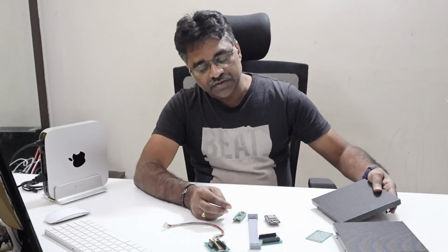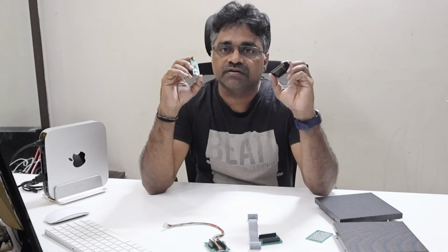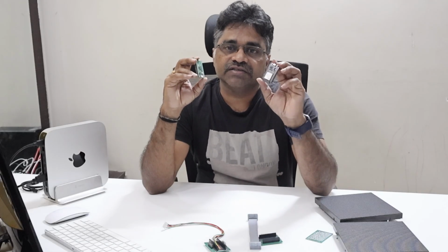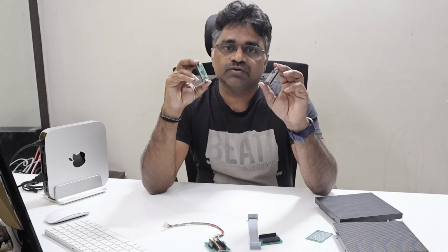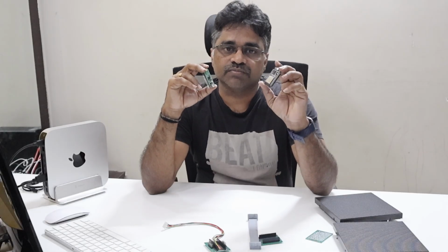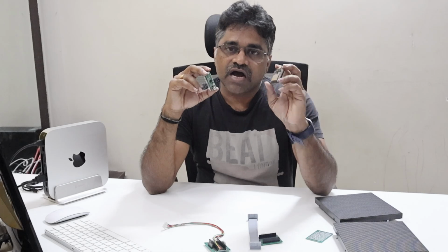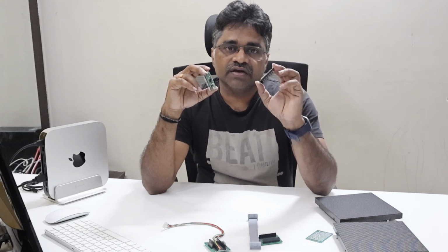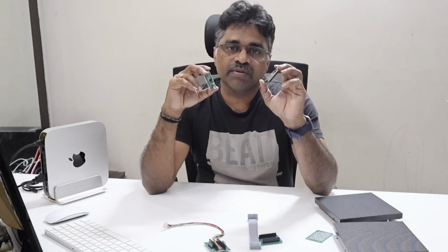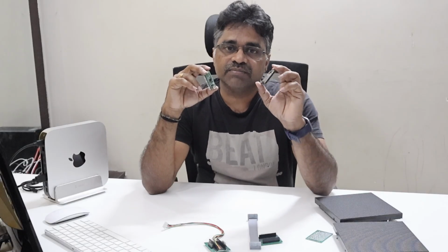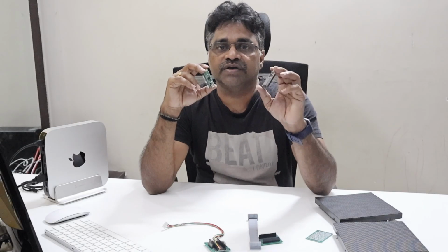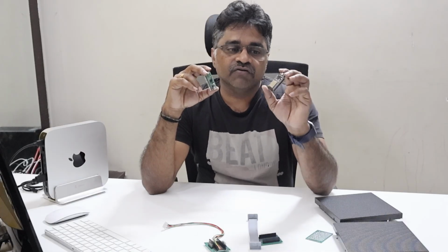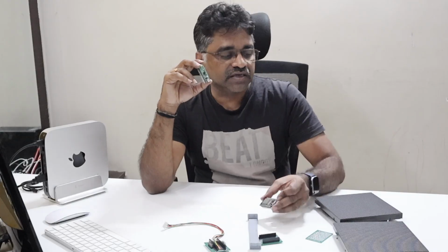To avoid that, I can use the two together. One is the ESP32, since it has Wi-Fi, Bluetooth, a dual-core CPU and DMA support. Considering these features, I will use it as the master controller, where I can connect from my mobile app, send some text or control my app UI. Then I can offload the rendering and panel driving logic.